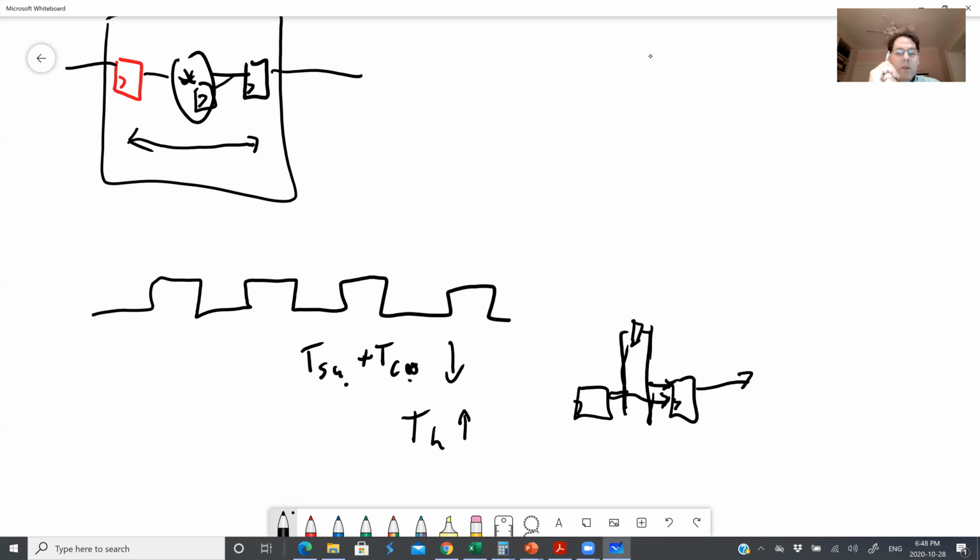Yeah, well, you do get reg-to-reg connections, so it's a valid concern. It is a real trade-off. Hold time is a real downside of pulse latches. It's just FPGAs can tolerate it better than most things. But I'm definitely not saying it's not an issue at all. It does make the FPGA router work harder if you get a lot of these hold violations, and it does chew up more routing, which gets to be a problem if it becomes excessive.